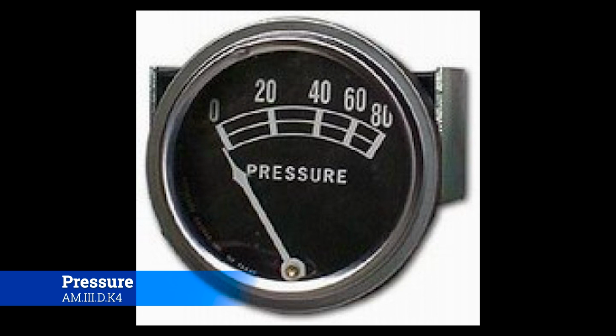You rarely ever see both of them go one way or the other together; they're usually going opposite of one another. And so there's an optimal amount of oil pressure, just like there's an optimal oil temperature, and that's where you want to keep it. If you have too much oil, too little oil, or too old oil, it'll indicate that on the dial as well, and you need to make whatever changes happen to make it work.